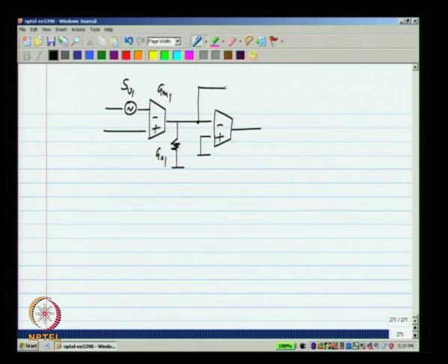Okay. One thing I will do is I will also ignore all the capacitors while calculating the input noise spectral density. So, it will be valid only for low frequencies, but that is okay, that serves usually as a good enough estimate of the noise. Now, let us say this is GM2. Now, I do not have to recalculate the noise from the first stage.